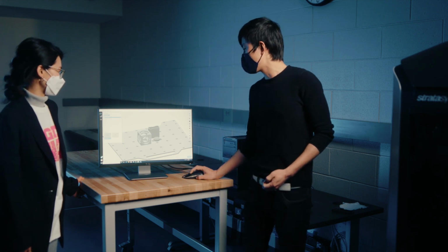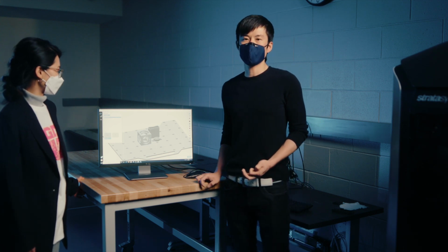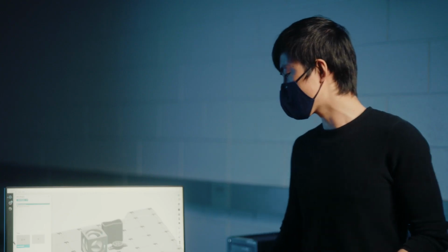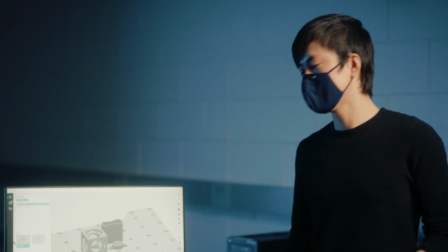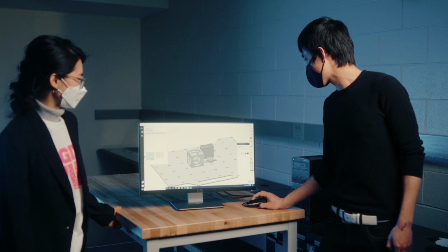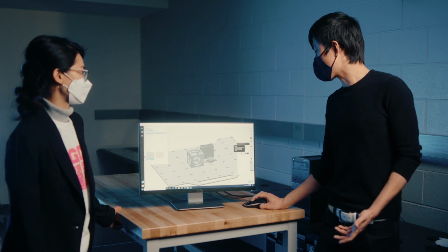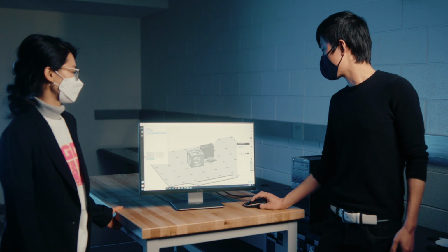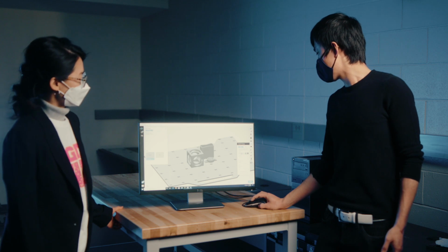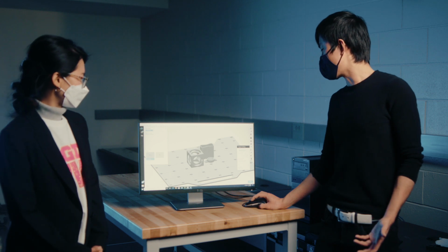In this case, when we want to print something like this, the structure integrity is not very important, but the finish is more important than the function. In this case, we can change the model setting. It defaults to high density, but we don't need it, so we can go as low as possible to the low density setting, which is an infill density of 13%. And then the support material, we usually let the computer do the calculating, so we pick the smart support style.